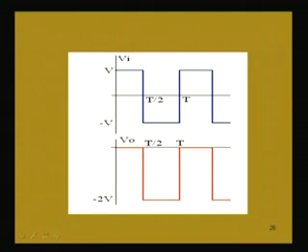So, we get this voltage. Here you can see that the voltage waveform given was this one, but now we are getting a voltage where the DC level is clamped at a different voltage. We are getting minus 2V, earlier it was minus V. So, the waveform is clamped at a higher voltage. This is an example of a clamper circuit.